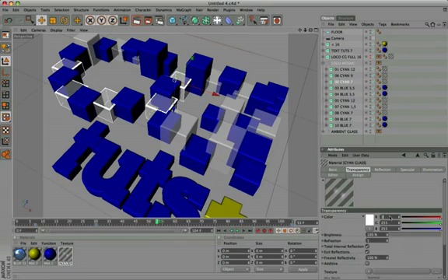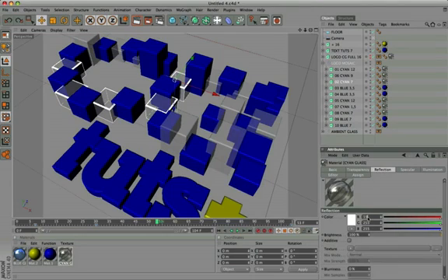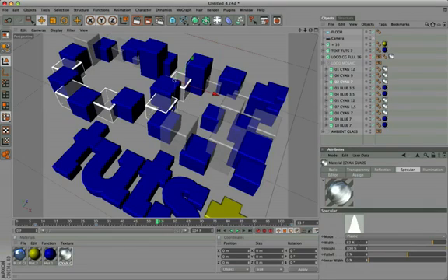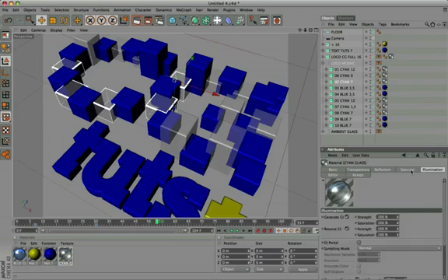Go to the transparency panel and insert a gray at 192. Modify refraction to 1.52. Go to the reflection panel and insert the following values: 150, 211, 255. Lower the brightness from 100 to 90, and activate additive. Let's go to the specular panel and enter values 82, 100, minus 17, and 4. The illumination panel is by default.